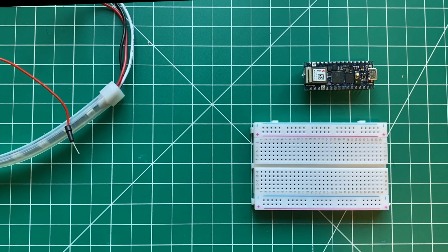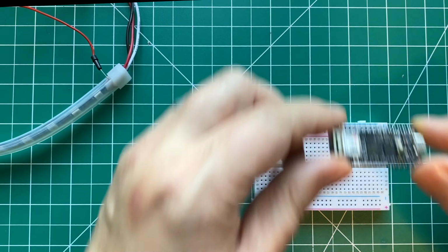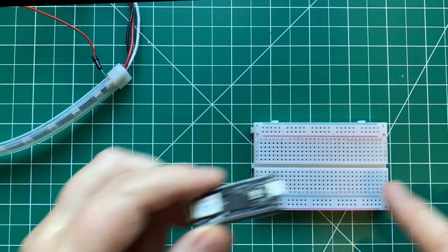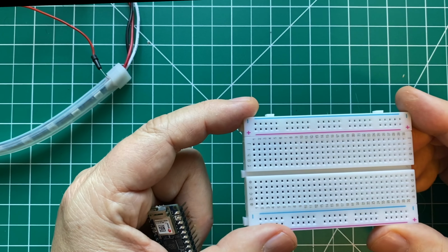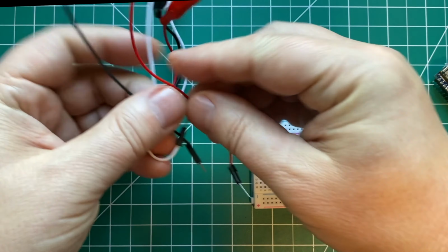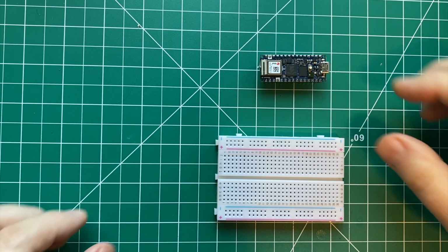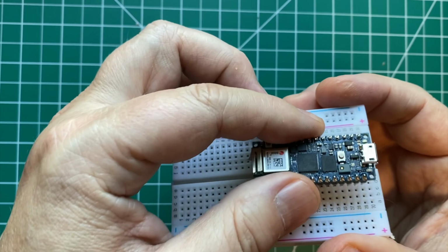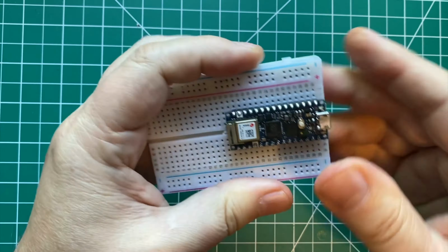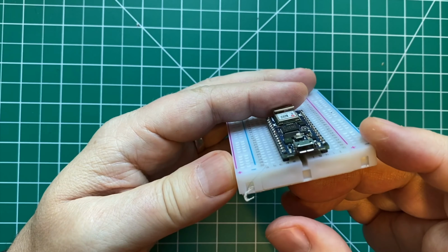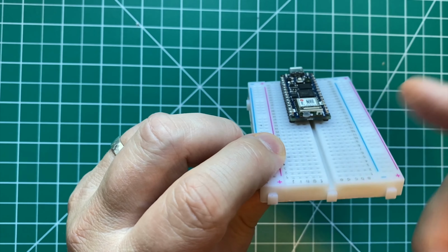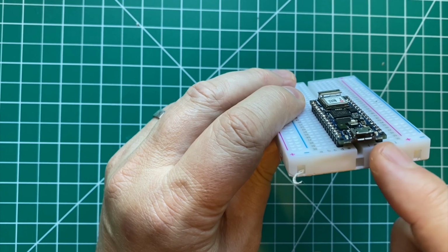Now here, for my Arduino Nano RP2040 Connect, this board has breadboard-friendly header pins. So I'm going to plug this board into the breadboard. That's this little plastic rectangle here, and the breadboard is going to help me easily set up connections between the pins on my board and the wires in my devices. Now I'm going to plug the microcontroller in like this. The header pins soldered to the board fit into the holes. Put your USB port to the side of the board so that your USB cable doesn't go over the breadboard. And notice when I plug my board in, these legs, the pins on the board, are straddling this gap here, the center line, which is sometimes called the ravine.